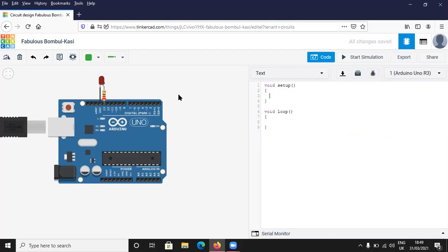Okay, sorry. We are just declaring the pin 13 because that's what we want to control. The ground is already there. So the ground usually you don't declare. You declare only the port number. And for that port number you use pinMode. So remember pinMode: it's pin, then the M is in caps. And then inside you have 13, comma, and you're going to have it as OUTPUT, like that. So you have declared that port as one of your outputs.